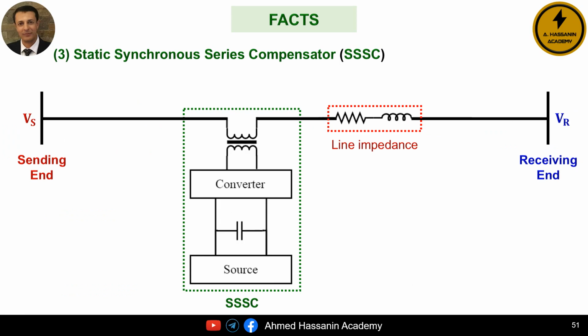The second point, as I mentioned before, is that SSSC devices are connected in series with the transmission lines. Therefore, quite simply, they can act as an inductive reactance, and thus they can work to impede the flow of electrical power. Consequently, they are capable of reversing the direction of electrical power transfer, and this, of course, is achieved through changing the phase angle.